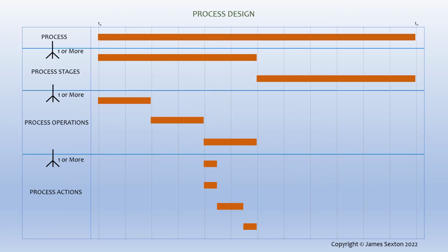In the case of the process model, the hierarchy is based on processes of smaller and smaller duration from top to bottom. We can think of the hierarchy like a Gantt chart, where the upper levels can be expanded to see more and more detail. We customize this general model to suit a specific process by starting at the top level and breaking the process down following the guidelines. We'll now do this using the example given in the ISA-88 standard.